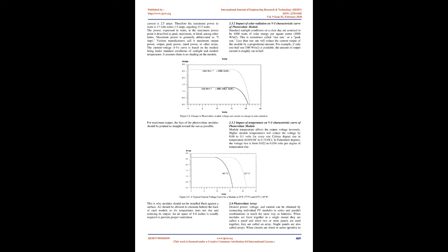The first regards the use of cadmium telluride thin films, the second concerns the development of novel nanostructured PV materials. Large-size industrial PV plants could have different characteristics compared to the small ones that, with few exceptions, have been realized until now. The analysis performed in this paper suggests to recommend centralized power electronic conditioning systems together with the use of proper simulation-aided design tools.